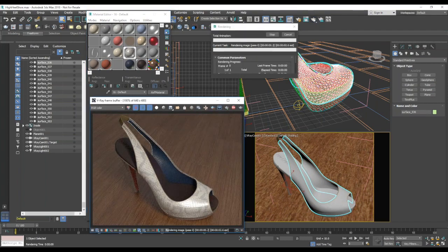And you can see now that my snakeskin material is showing up with a bunch of other AxF materials that I have assigned to this shoe. And just like that, I have a rendering using the AxF material. So that part of it has been streamlined quite a bit and is working really well at this point.